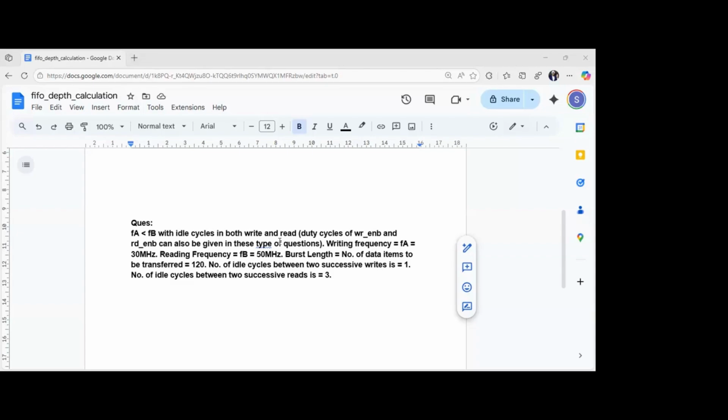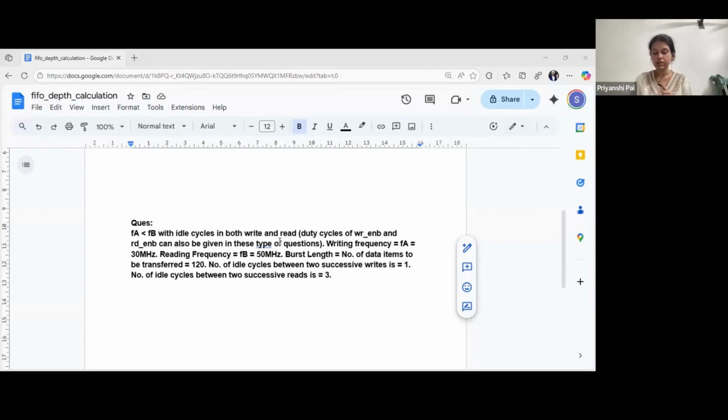In UART, what have you made? What is the purpose of the UART? Ma'am, UART is basically used for serial data transmission. There are two transmission lines in UART, TX and RX. Also for UART, we don't require any clocking pulse for synchronization. That is why it is also known as asynchronous.